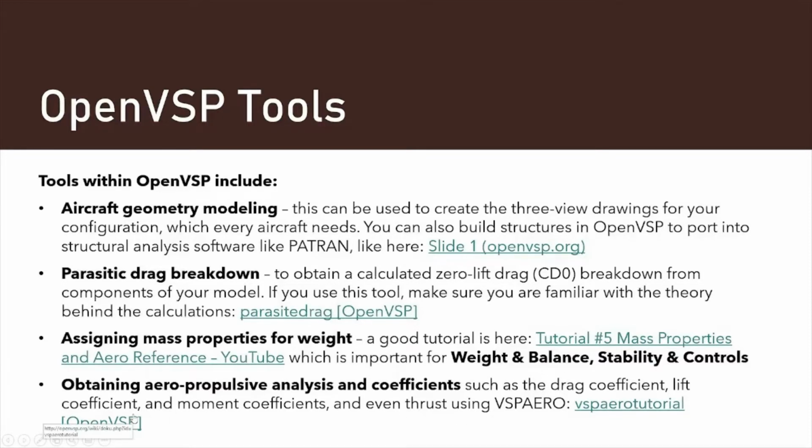Actually, even though I don't have it linked anywhere, I published a paper with NASA Langley, and this is something that we did. We basically compared the results from OpenVSP for the X57 wing, for the drag, lift, and everything, and then plotted it against OVERFLOW and another software called Robin. And basically, it performed pretty well. I mean, the moments are a little bit difficult to predict, but lift and drag was good.